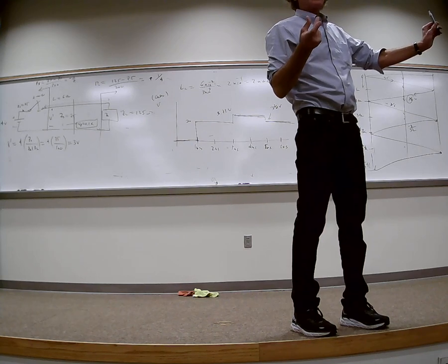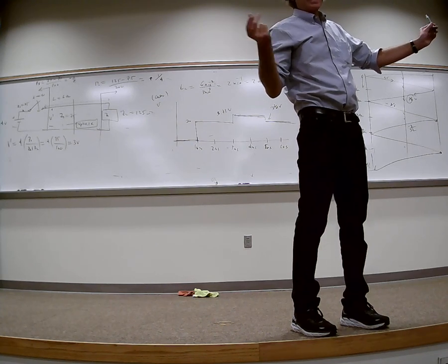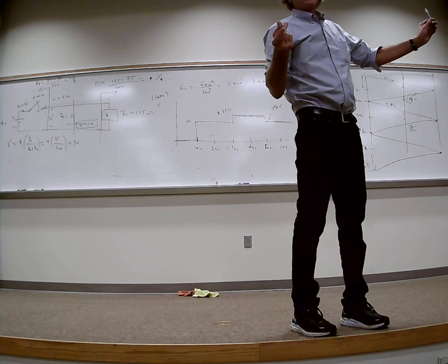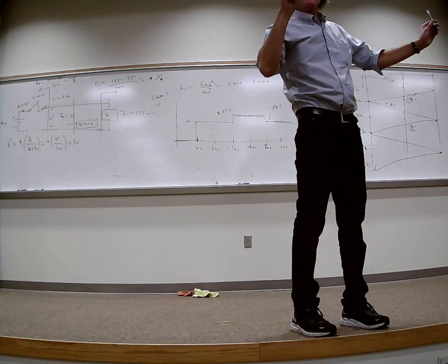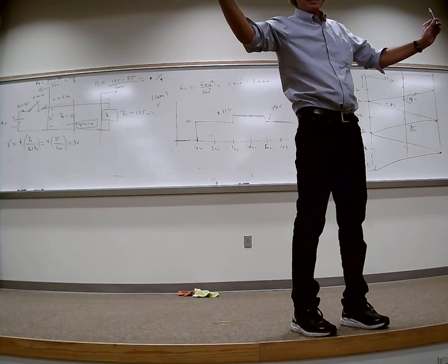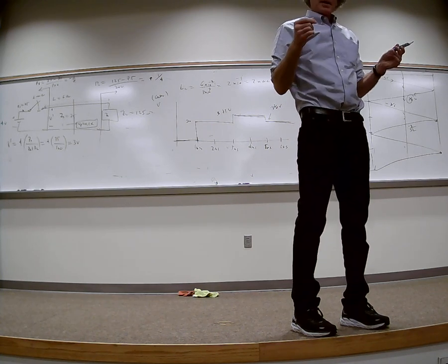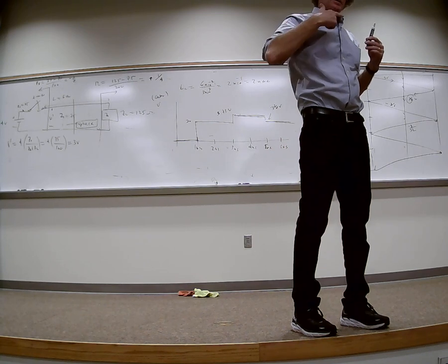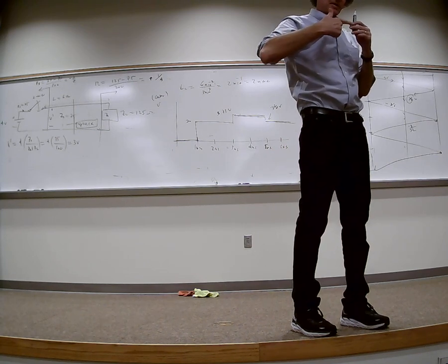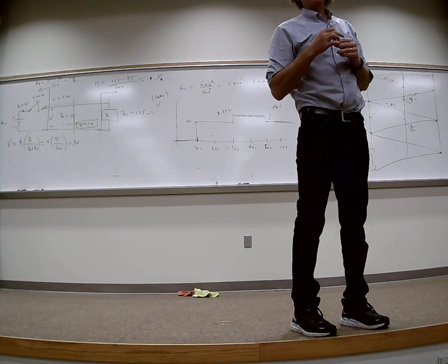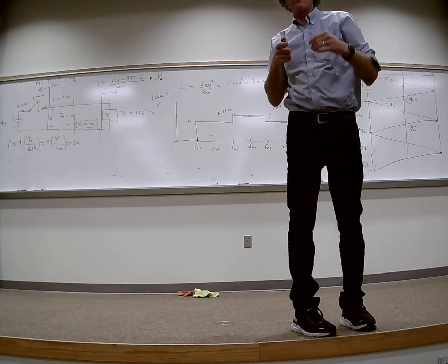So they'll know the velocity of the wave on that Cat 5 or transmission line. C times that time is 2 times the distance it went. So it takes C, or the velocity on that, times the time from when you sent the pulse to its reflection, and they'll divide that by 2, and they'll figure out how far down the line it is.